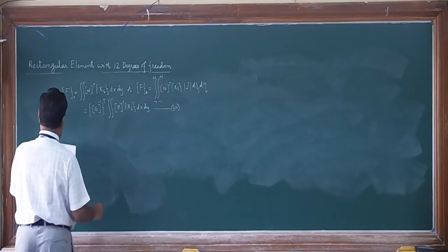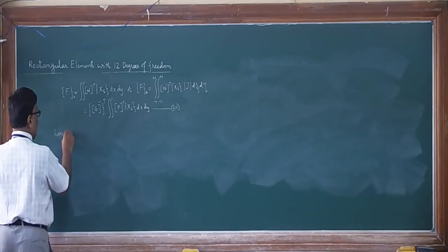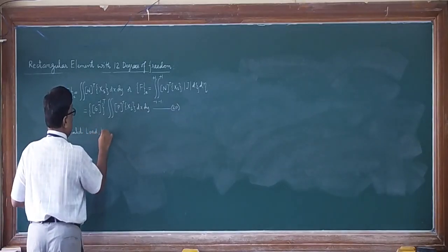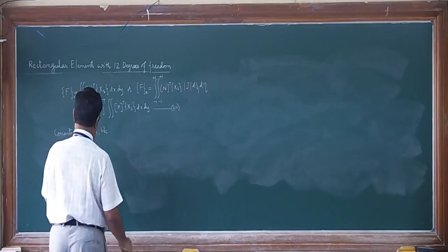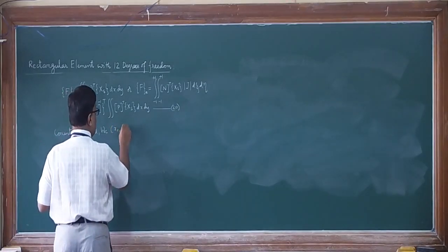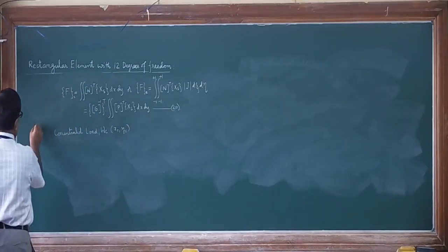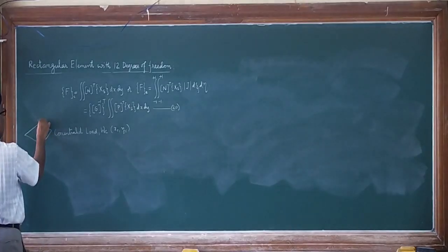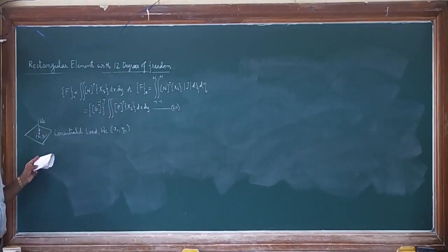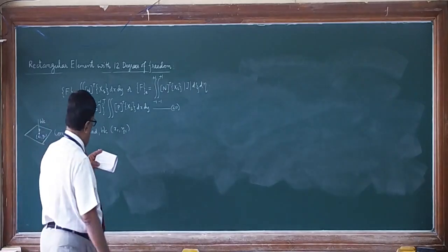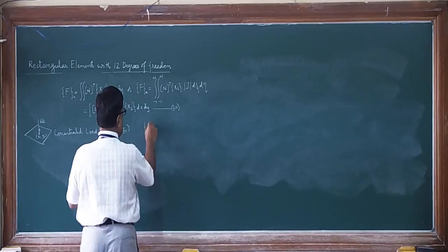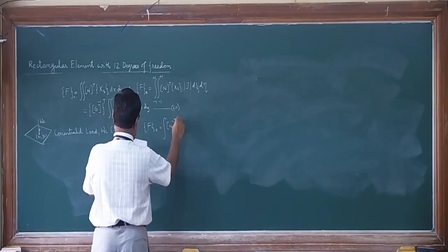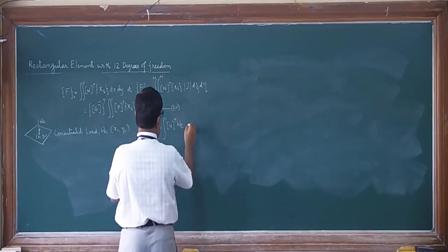And if you have a concentrated load, for example, let us say WC, it acts at the center of the plate, or whose coordinates are XC and YC. This acts on a plate. For example, if you have a plate here, and if this is your XC and YC, and if the load is acting here at WC, how to take into account this load vector into the equation that is given by FC is equal to N transpose WC. Okay, this is what we can write.